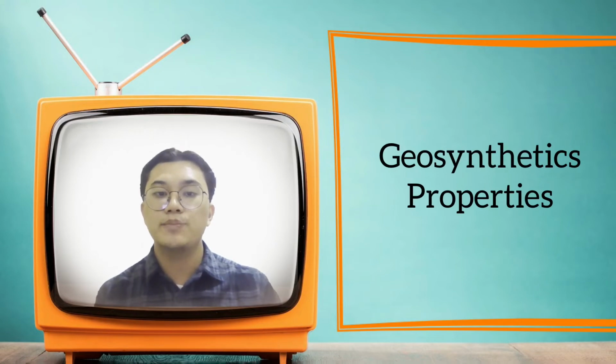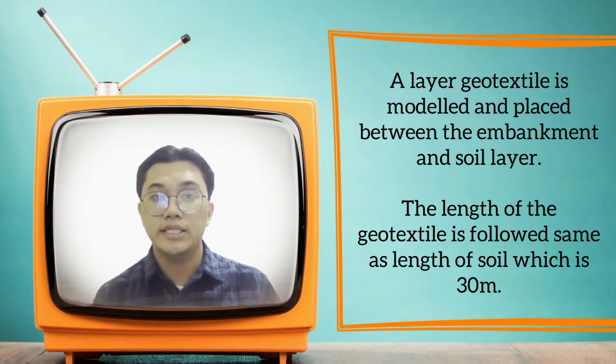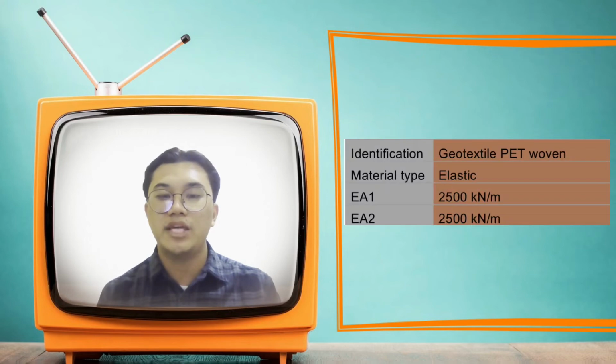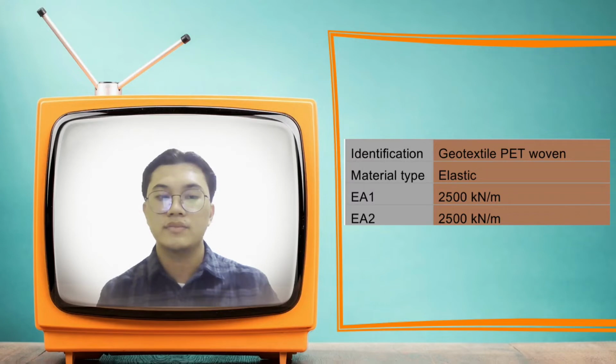Next is the geosynthetic property. A layer of the geosynthetic is modeled and placed between the embankment and the soil layer. The length of the geosynthetic is the same as the length of the soil, which is 30 meter. The value of the tensile element, or the geosynthetic stiffness, in Plaxis is known as the EA. The geosynthetic property follows the previous research by Silvanshnia 2010. The identification is geotextile PET woven, the material type is elastic, and the geotextile stiffness is 2500 kN per meter.